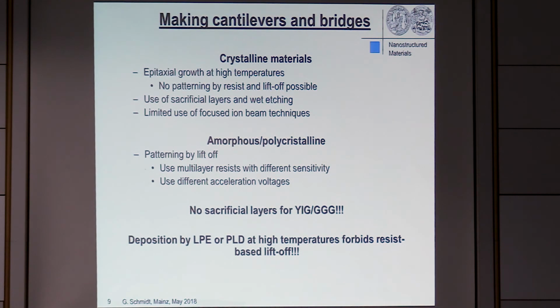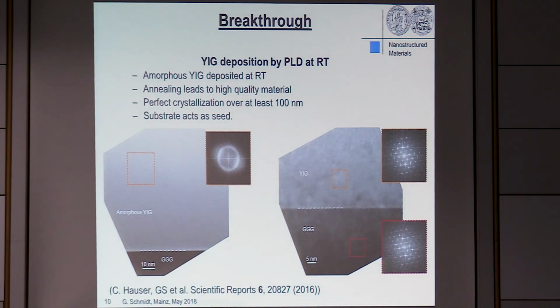And the deposition by liquid phase epitaxy or pulsed laser deposition forbids patterning by lift-off because you will simply burn the resist in this case. Now the question is, is there a way to combine lift-off with crystalline YIG? And actually there is a way. And this way came to us a few years ago. It was in the frame of a European project.